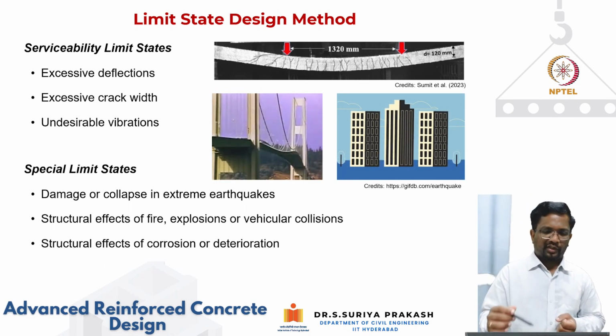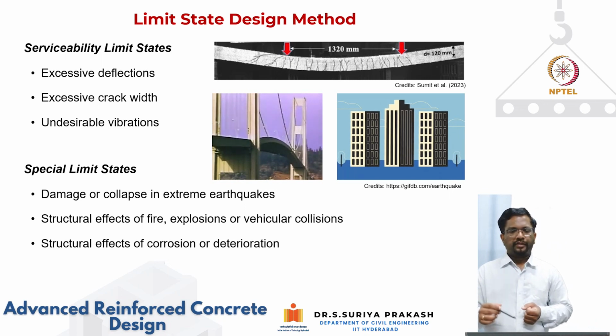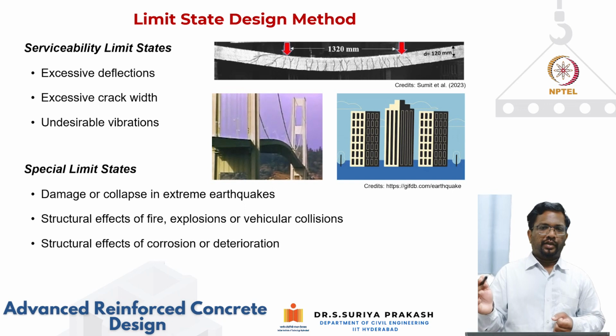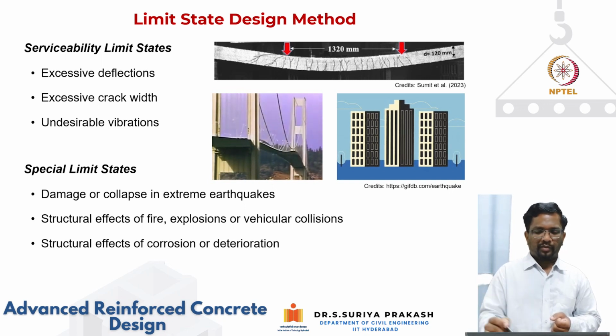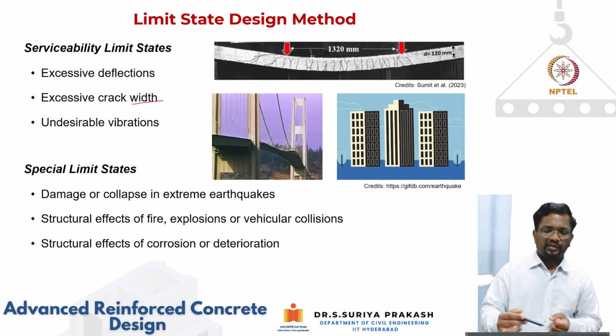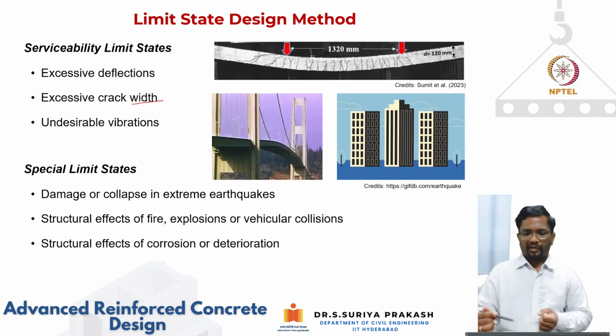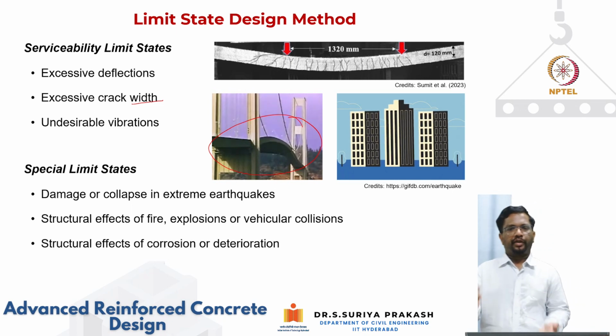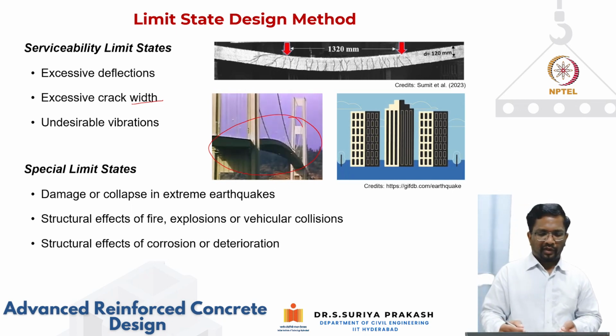Now we'll talk about serviceability limit states. Again, the structure should be serviceable as well. So it has to satisfy the allowable deflection requirement, and crack width has to be less than a certain value, and the structure cannot vibrate. For example, you see here, this is a suspension bridge. If it is vibrating, of course, vehicles cannot travel on it.